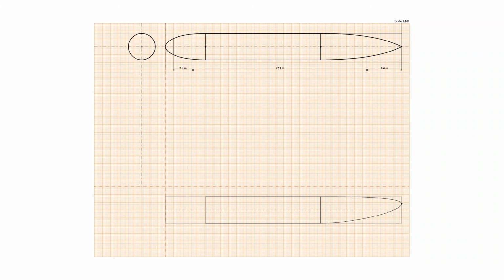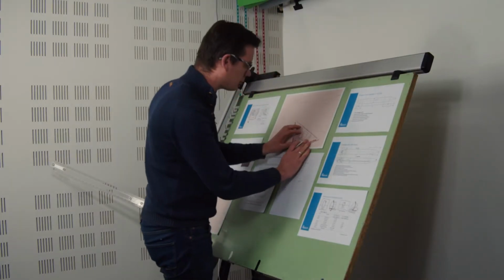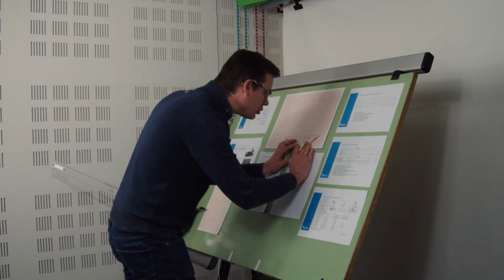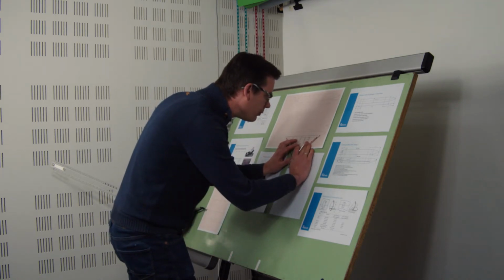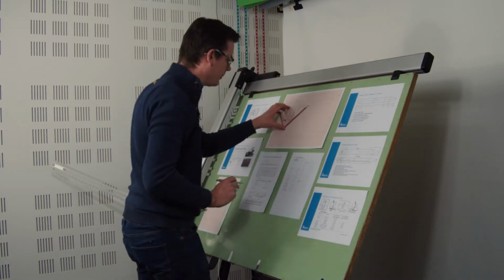And then let me also, just to make sure that I cut off the floor at the right location, draw in the location of the aft pressure bulkhead. In other words, the end part of the cabin, which ends over here. All right, now I can draw in the floor, because I remember that it was 22.1 meters plus 1 millimeter.